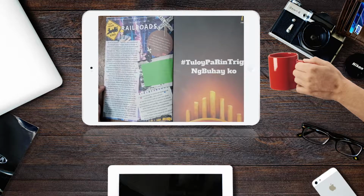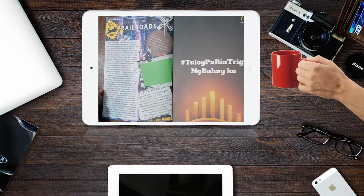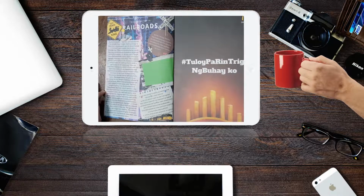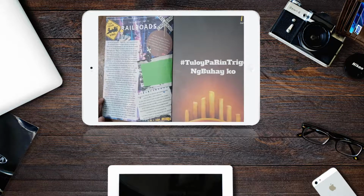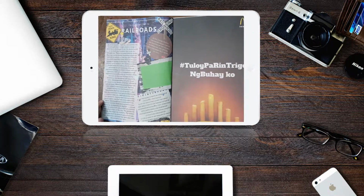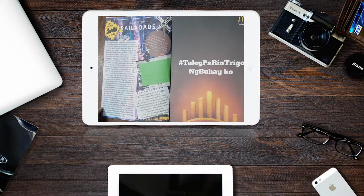The first proper railway was the Liverpool and Manchester Railway, which opened in 1830, like the tram roads that had preceded it by over 100 years. The L&M had gentle curves and gradients. Among other reasons for the gentle curves was the lack of strength of tracks, which might have overturned if curves were too sharp, causing derailments. There was no signaling at this time, so drivers had to be able to see ahead to avoid collisions with other trains on the line. The gentler the curves, the longer the visibility.